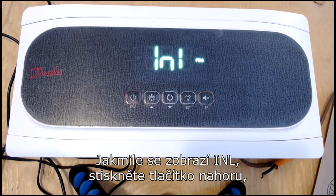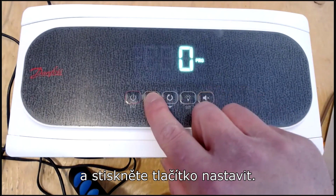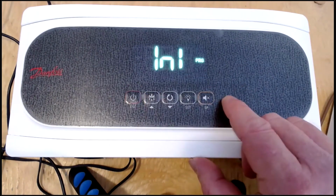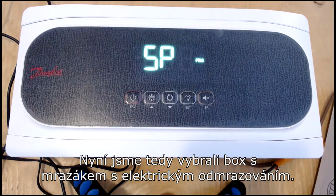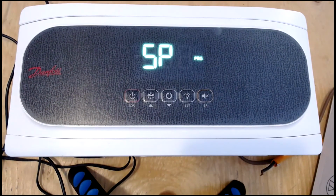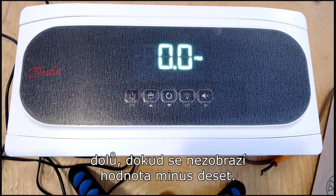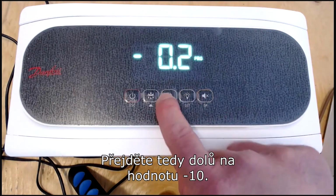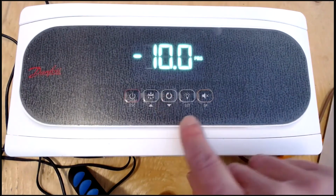Once INL is displayed, press the up button to select the number of the program to be used and press set. In this example, we will select program 3. So we have now selected a cooler freezer with electric defrost. SP will display on the controller. Press set and then use the down button to scroll down in value until -10 is displayed. Press set. So let's scroll down here to -10. Hit set.